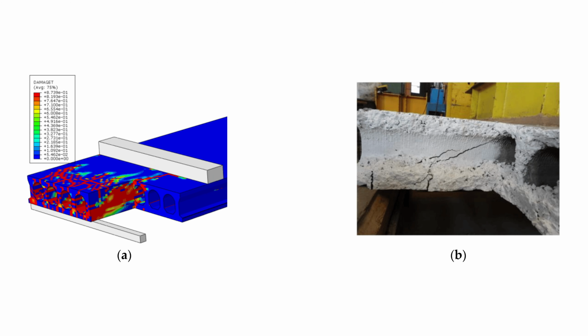So what I understand is there's no point in improvising by filling concrete into the hollow core holes at site. Secondly, if you're not doing that, then a hollow core slab is not really recommended for a ramp because of the distortion it can cause, the change of center of gravity. Yes, and the crushing of the concrete, which is more governing to crushing or compression.